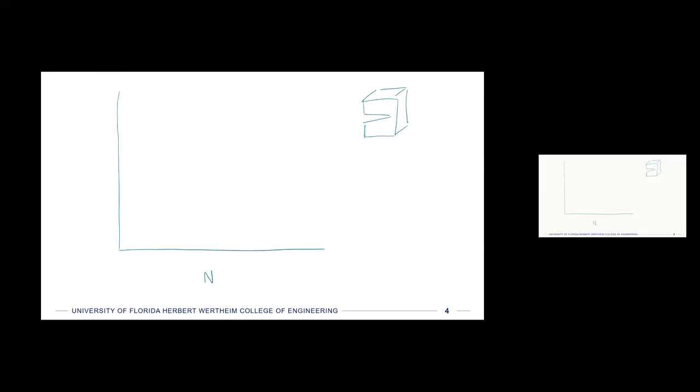And so it's got some notch with a crack, sorry, I didn't draw that very well. And then it has loading that wants to open that thing in mode 1. And so now we're measuring the crack growth over some number of cycles at constant loads.